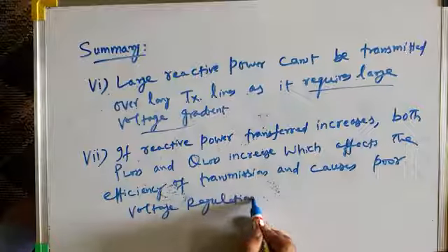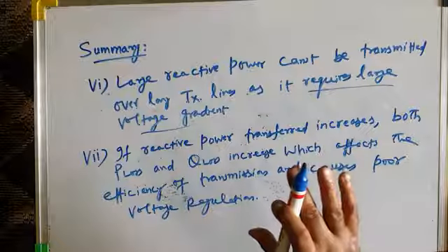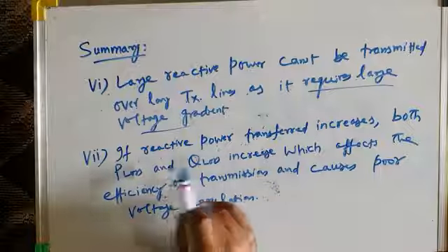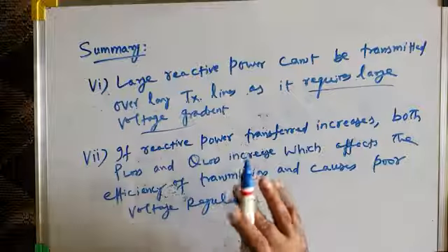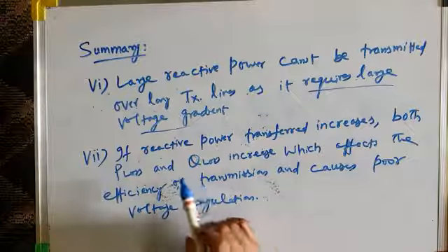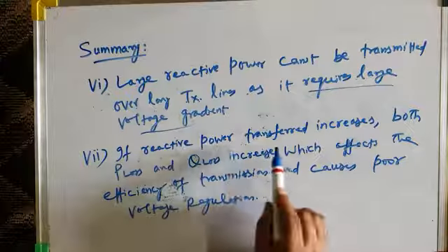Try to understand this point. For the same active power demand, if reactive power changes, because I told you that depending upon the timing of the day, sometimes industrial load increases, sometimes industrial load decreases. The rise in industrial load means more deterioration of power factor, that means more reactive power transfer.